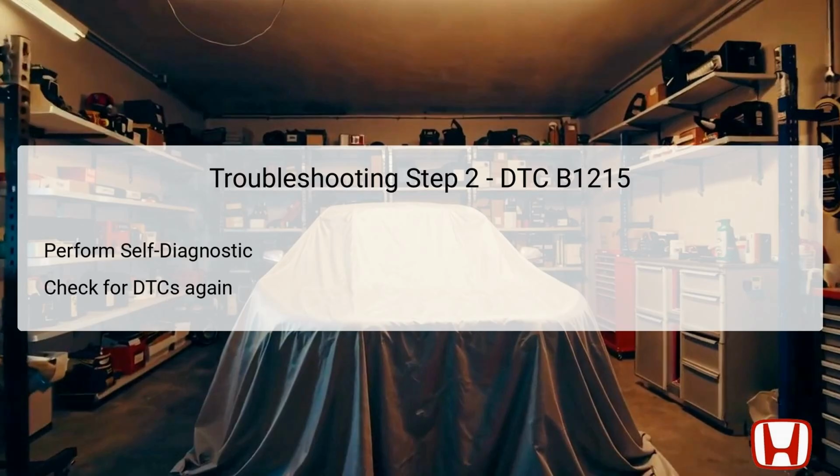After performing this function, technicians should check again for the presence of DTCs, specifically looking for DTC B1215. If this code is indicated, it affirms that the problem persists and requires further investigation. If not, it may signify an intermittent issue, prompting a check of wiring and connections to ensure the system's integrity.